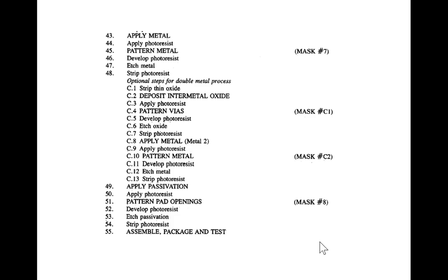What if you mess up one of these steps? Can you strip it? Usually not. Once in a while you can mess up a step and redo it. Most of the time you mess up a step, you have a wafer breaking party. And you're not popular if you break wafers. Okay? So bottom line is, every one of these steps needs to be accurately done in the right sequence. You mess up any one of the steps, and usually you have to throw your whole partially completed wafers away.